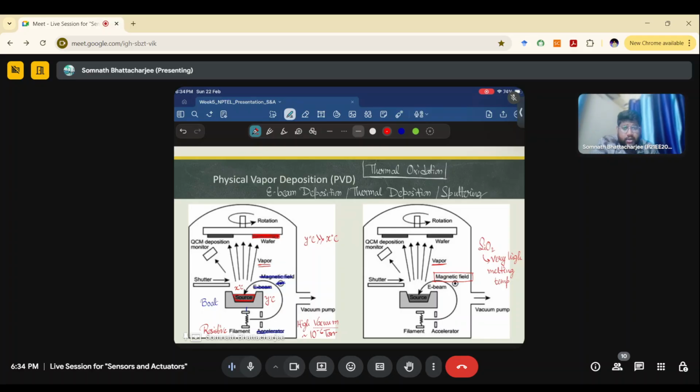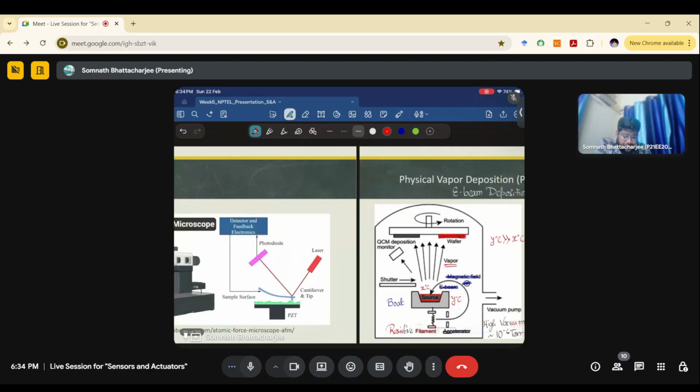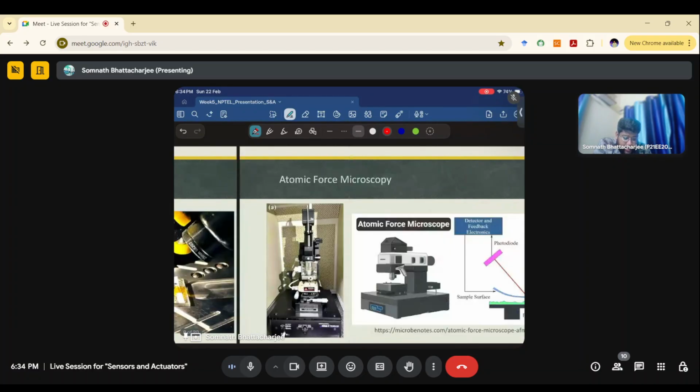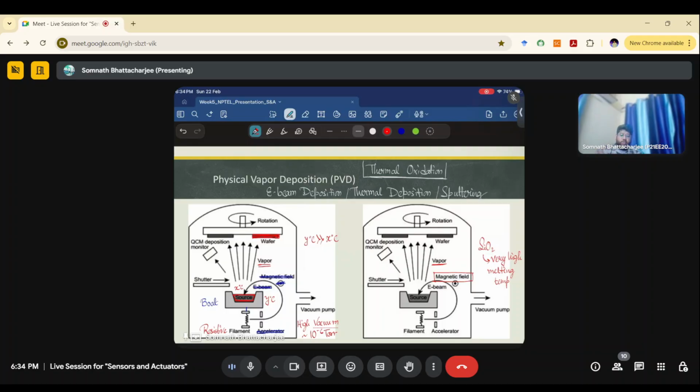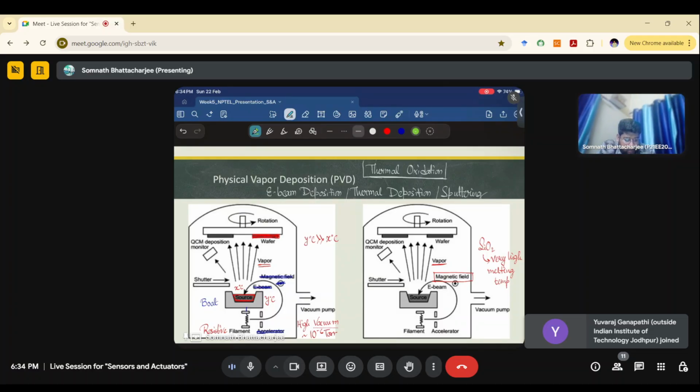Now, as we have already discussed these deposition techniques, based on our discussion so far, we know that we have deposited silicon dioxide on top of the wafer itself. Previously in thermal oxidation, if this was your silicon, your new silicon wafer would be like this: the top part will be silicon dioxide completely, and the bottom part will be silicon.